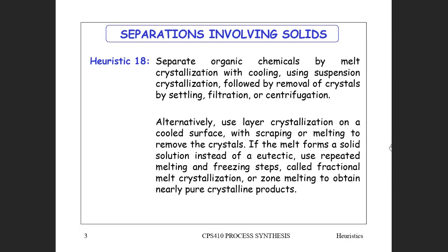to crystallize something, you can get separation without using a great deal of energy. When you do distillation, you always need to have a reflux, and therefore a lot of energy in steam usage. You've got to put in energy to get that separation occurring. I've talked about it before, maybe not with this class.